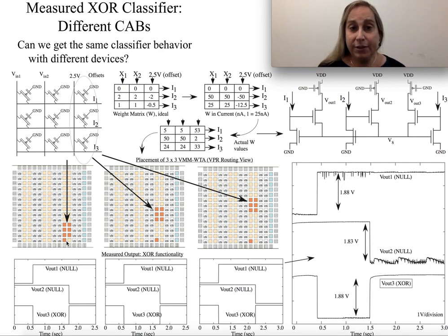Now, to think about this, you might say, well, first, how do I transform the weights? What's really nice is that there are some transformational properties that allow me to do some invariance, do some scaling, and allow everything to be one-quadrant multiplications because of the beautiful common mode rejection properties of the winner-take-all structure. It's a generalized approach.